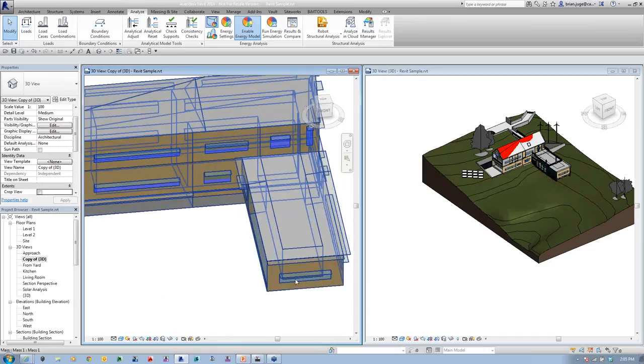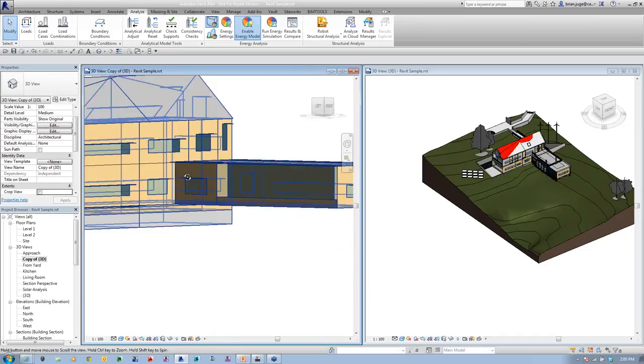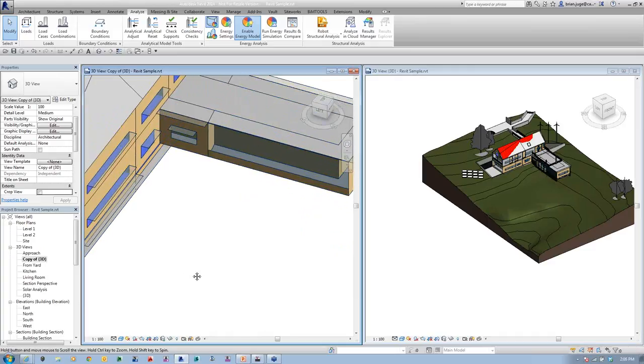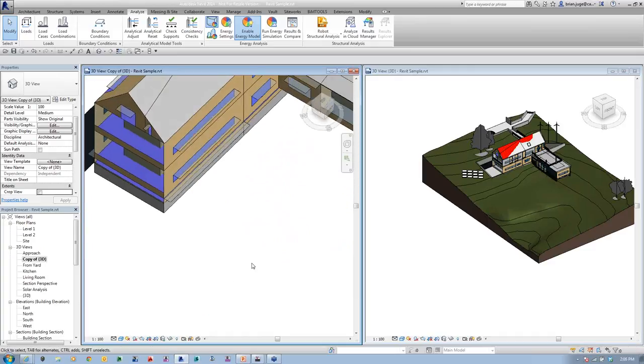But you can see in here, now I've got different shelves. Just by clicking on that, I've got some shading being done to those windows to give myself shades throughout the year. And that's going to primarily be based on when do you need to start heating the building, when do you start needing to cool the building. So that weather station data you're getting out there is going to determine how big these solar shades, these shading devices, need to be within our project.